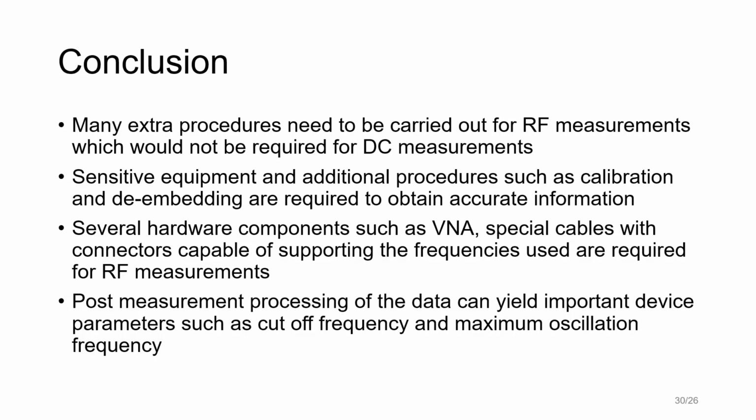Calibration and de-embedding are necessary to obtain the real characteristics of the device alone, without the effects of the system or the parasitic networks. Although the measurements immediately give us the S parameters, after performing de-embedding, we can obtain a lot of different kinds of information about the device.